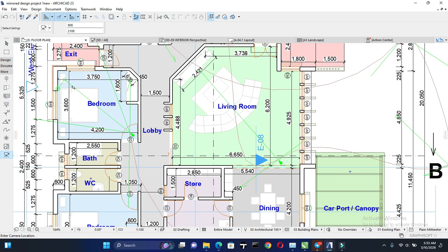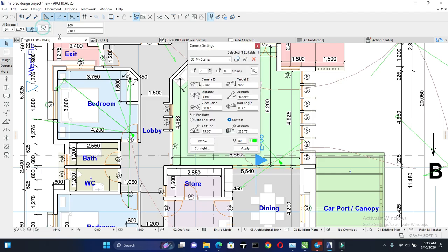So I am coming into the room, my height is 1800, or let's use my height is 1500, 1.5 meters, and I'm looking at 900. That's looking at the bed on the sill level, practically on the sill level, so it's going to be showing the bed. So let's see, we've done that, apply, and then let's go and find camera 7. So close, go to the views, camera 7. That's the one I just clicked, as you can see.